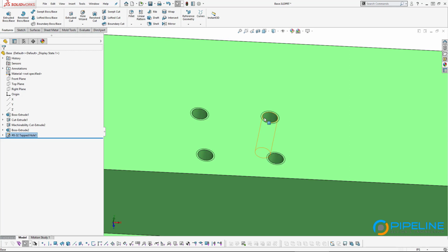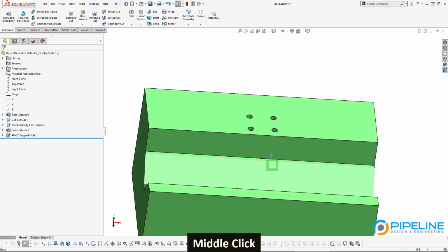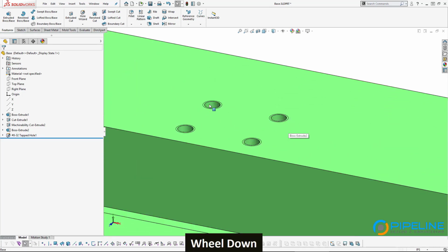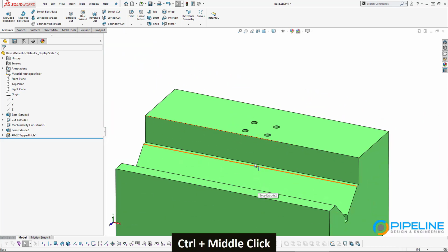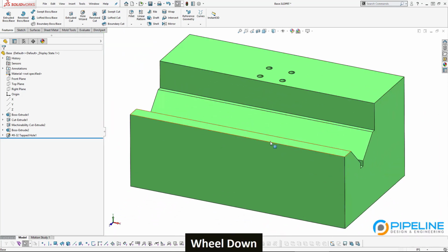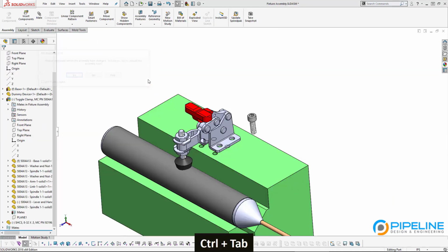If I tell the machine shop, drill a hole here at this point and make sure that it has an 8-32 tap, then they'll be able to do that, and they don't need to see the helical shape. So we're all set here. There are some other settings to make this look more apparent, which we can talk about in a later lesson, but this is what it looks like by default apparently. Looks different on my computer because I must have changed it a long time ago.